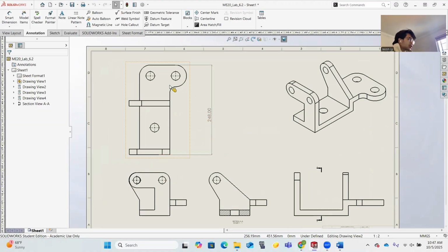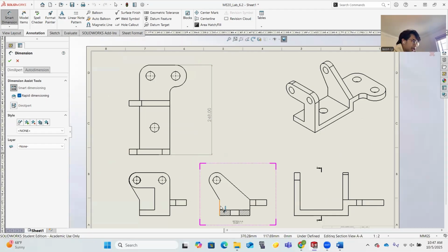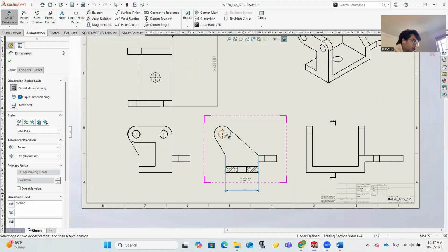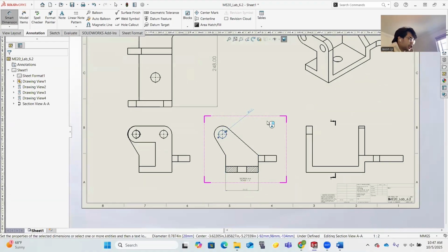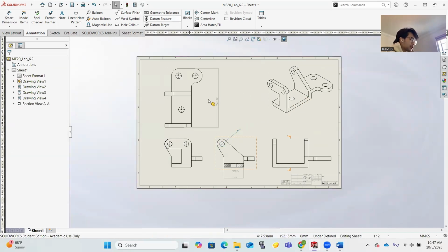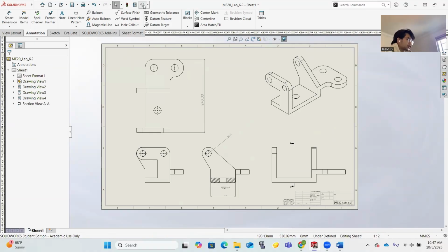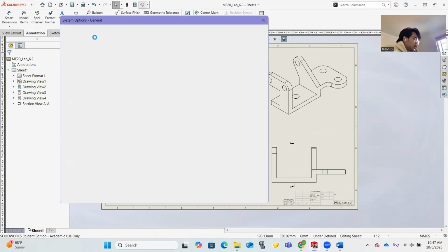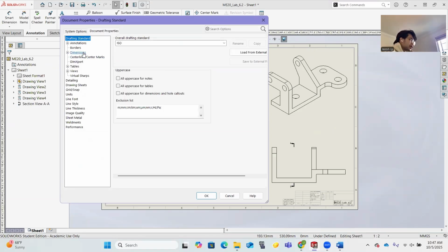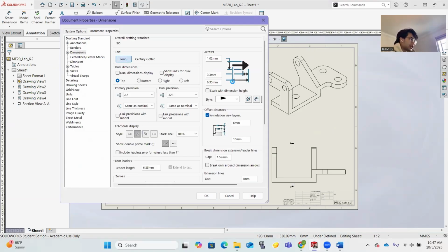So going back to changing the number size, that's pretty tedious if we have to do it for every single one, right? Like if we want to go like here to here now, this is super tedious, where we don't really want to look at all these numbers or change them manually one by one. So what we're going to do is go to the document properties and actually change it ourselves. So we're going to go to this gear, go to document properties, and then go to dimensions, and then go to font here.